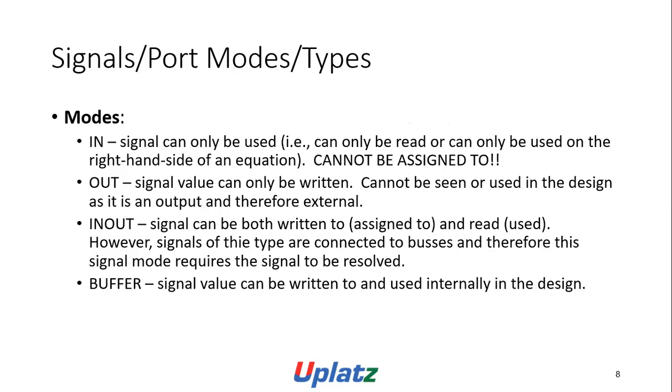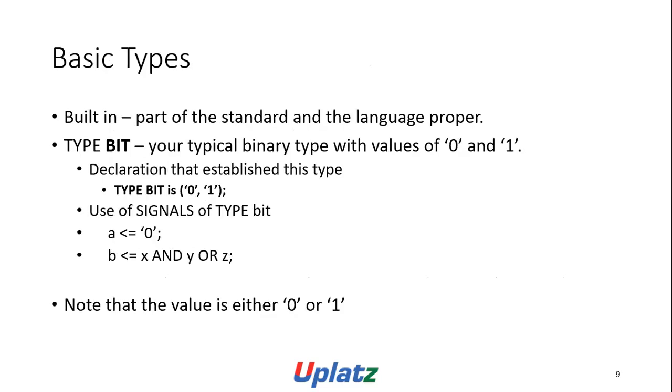Mode inout: the signal can be both written to, assigned to, and used. However, signals of this type are connected to buses, and therefore this signal mode requires the signal to be resolved. Mode buffer: the signal value can be written to and used internally in the design.